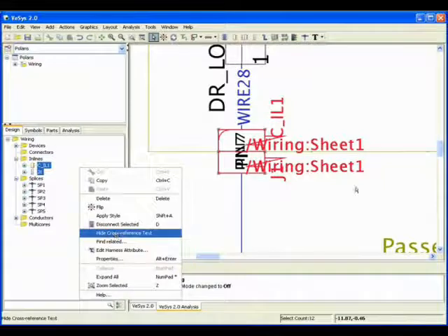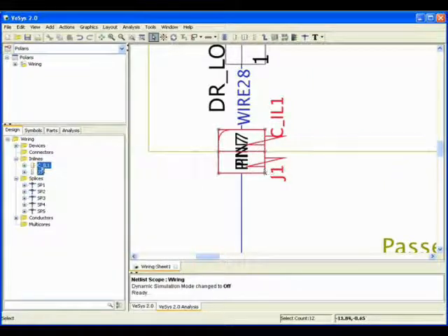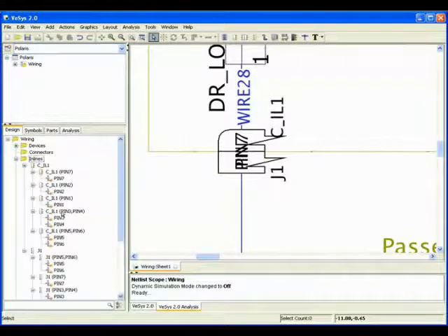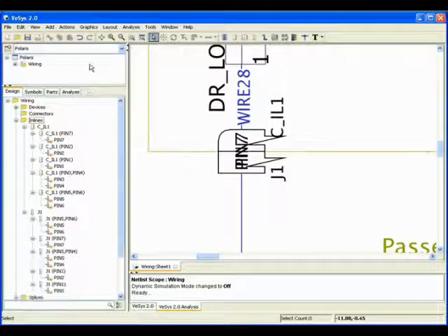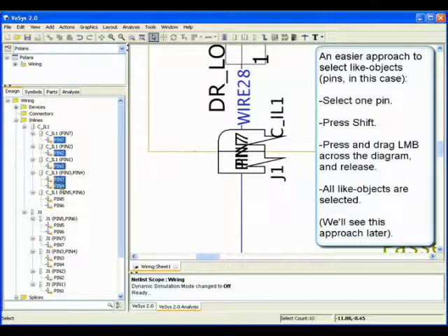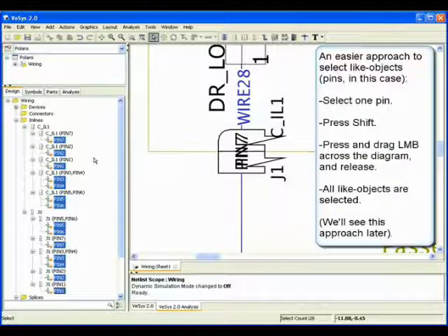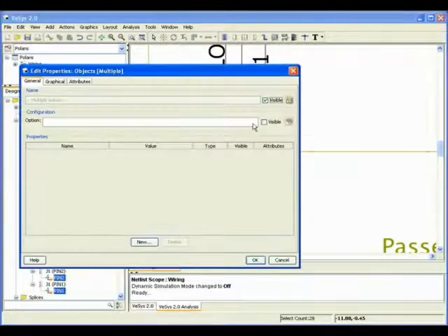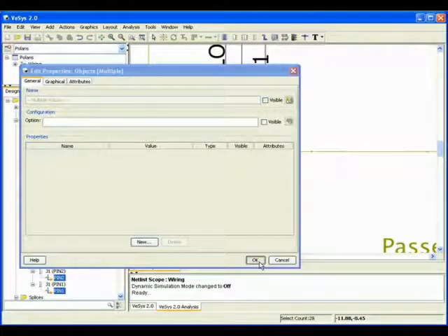Notice we can select both the objects of the inline pair and hide the cross-reference. We want to remove all pin names. We could predefine this behavior using the Style Set facility, or in this example, change it on the fly. First, expand the inline pair in the Design Browser tree, and then select every pin. We can then click Properties and uncheck the visible box to hide all the pin names.